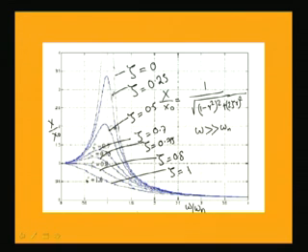So, you can see that with an increase in zeta, that is, increasing the value of the damping ratio, the maximum amplitude of the system decreases. So, by using this damping, when the response is near this omega 1, you can decrease the resonant amplitude of the system.